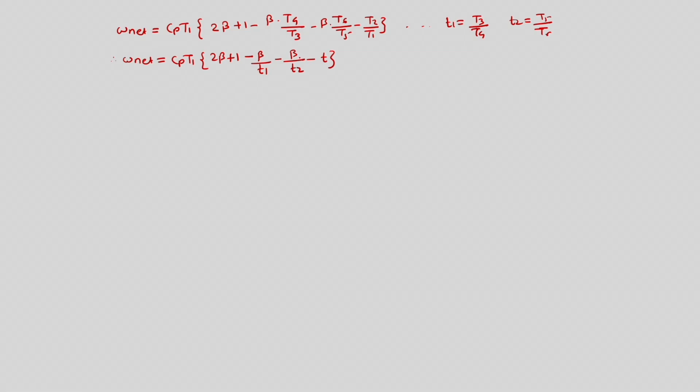So here now we will say that we are working with same or constant Cp, beta and T. So the variable is only T1 or T2. So we are not altering compressor work, we are not altering the maximum and minimum temperature ratio, we are not altering the working medium. So we are just altering the pressure at which we would be doing the reheat. So here we are just altering the exhaust temperature to the high pressure turbine.